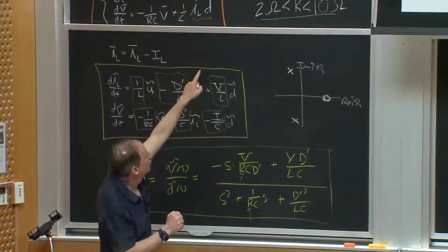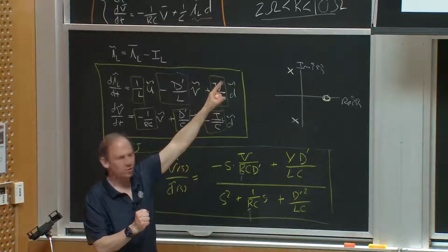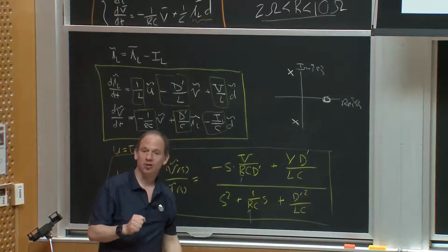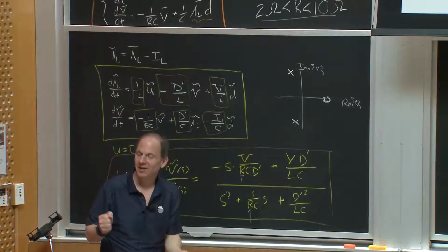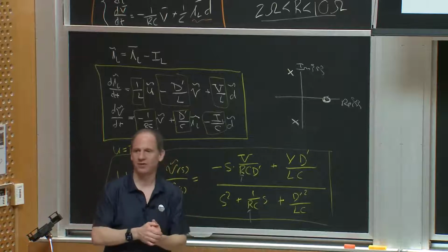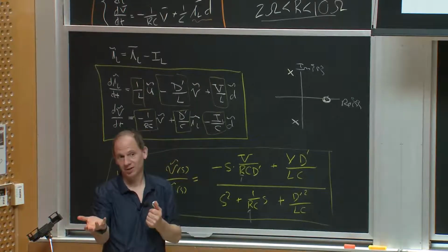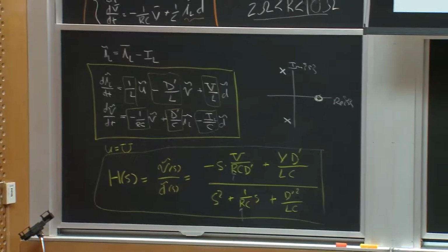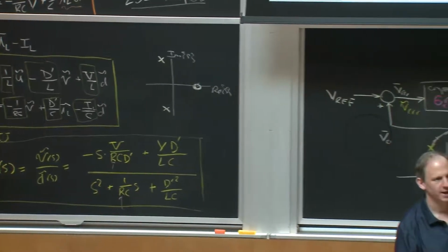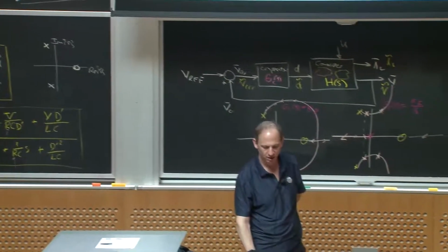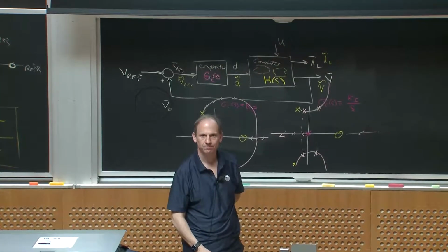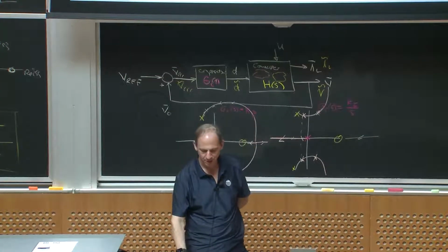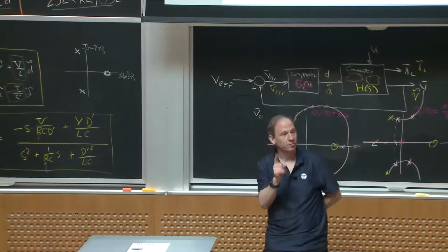Okay? The resistor damps that. Right? So it's some funny modulated version of the LC oscillation with a parallel resistor. So basically it's like a parallel resonant tank, and the resistor is what's damping that thing. If you make the R big, the damping is small and it oscillates more. So it shouldn't be surprising that the location of the open loop poles gets closer to the j omega axis and less damped as R gets bigger. Okay? So I might really have trouble if my R went to 100, but I'm only making it go to 10. Okay? Notice that also things vary with input voltage, right?